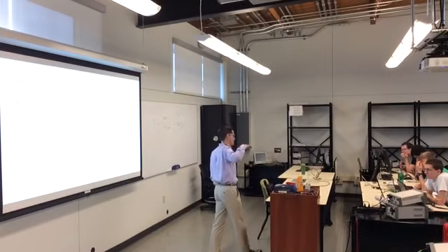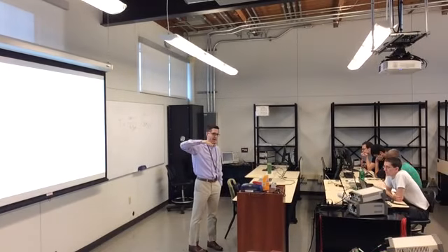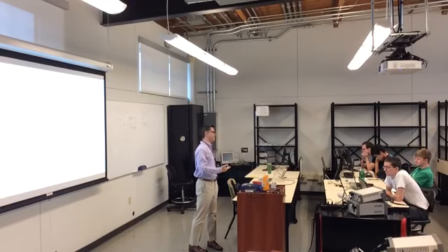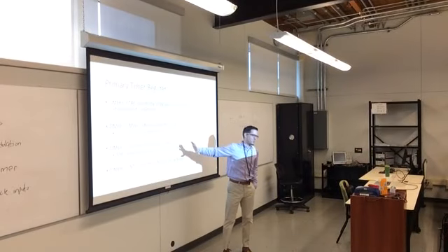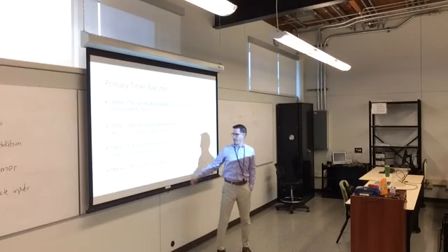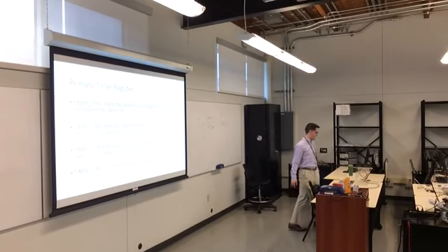You can read and write its send and receive registers automatically, but you might get data in the middle of transmission. So there are generally some buffer registers that allow you clean atomic access to those objects. And then count gives you the current count of the register.